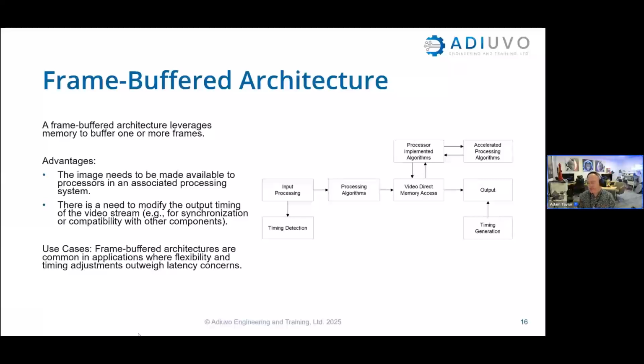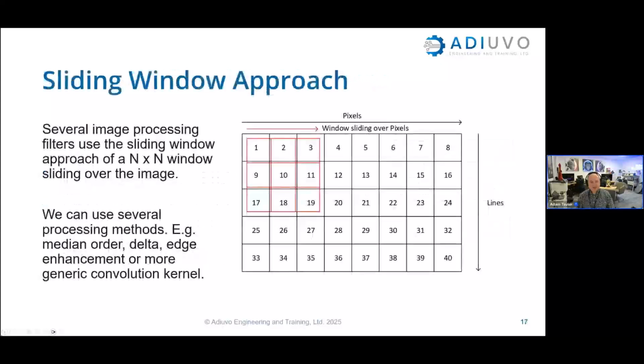The idea with the demo today, and what we've been talking about today, is to give you an understanding of how to do that, and a reference design of how to do that. There's a reference Vivado design available on the GitHub that I linked earlier, that you can go and get and take through, and then start working on it yourself. We're just doing a simple pass through for this example, but you can start adding in image processing elements that you want, and such like.